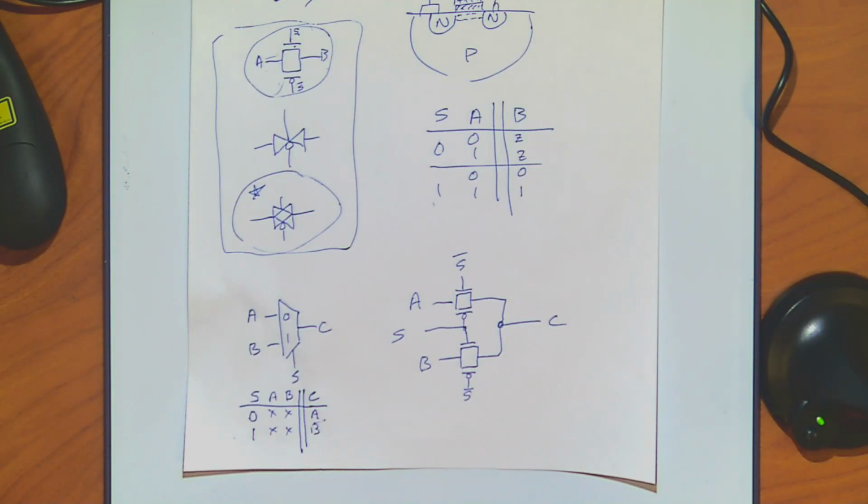All right, for a mux, that's a pretty nice result if you think about it. Space-wise, that's really efficient. And I get really good transmission of the signal, and I can use a mux design. And once I have a 2-input mux, this is an if statement in Verilog. I can implement an if statement with 4 transistors. And if I want more, I can just cascade them. It's a binary tree. So you just build your binary tree, you build it as big as you want.